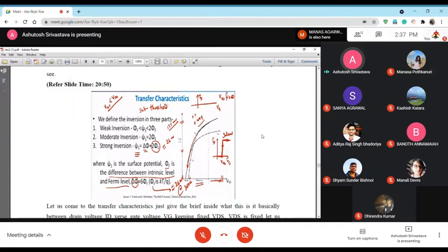And because of the basic physics, the type of material that we are using in the MOSFET transistor being silicon, most probably working at room temperature, it restricts the so-called subthreshold swing, which can be determined by this graph, at 60 millivolts per decade.